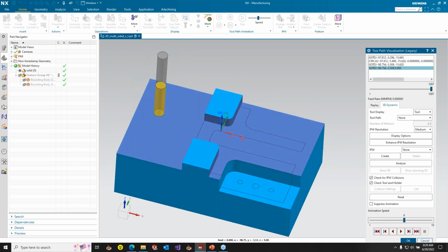So the feature recognition code is really awesome. I mean, it's not the end-all be-all of geometry selection. So for sure, you will sometimes be creating a sketch and controlling the toolpath with a sketch in NX. We're picking it off the model.